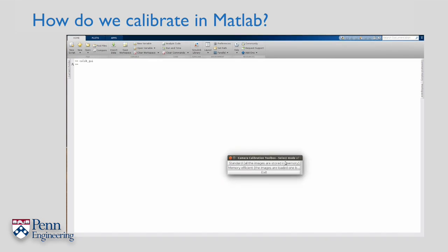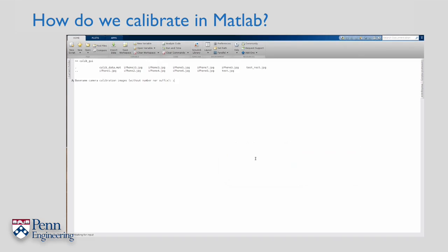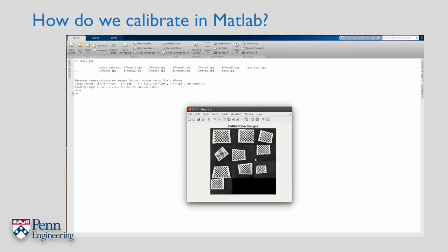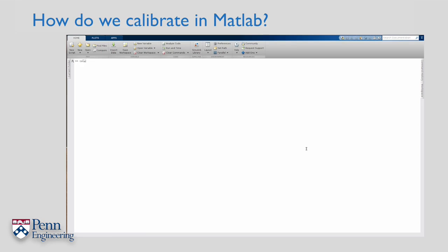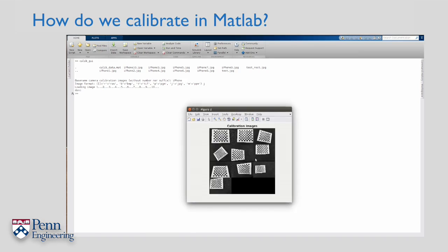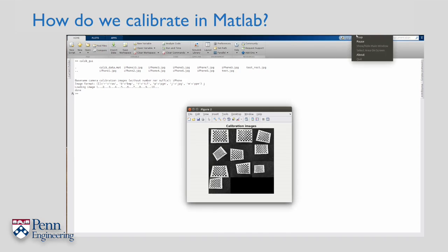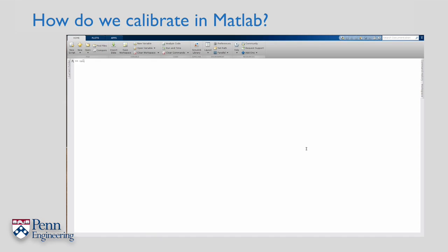We're going to use what is called the calibration toolbox. After we have downloaded the calibration toolbox and we are in the directory where it lies, we call a GUI, a graphical user interface, and then we have a menu where we select to load our images. These images are the images of a checkerboard. That can be, for example, 8, 10, 12, or 20. And then we have saved them in a directory and we load them all in memory.